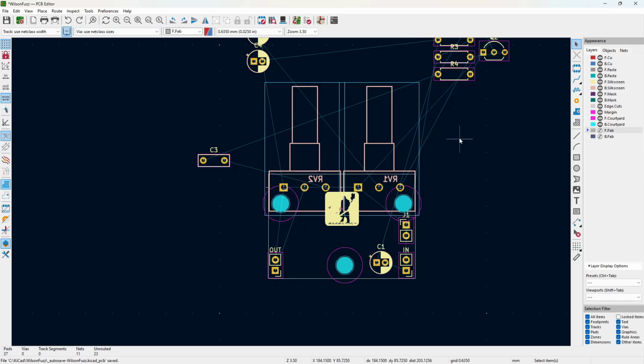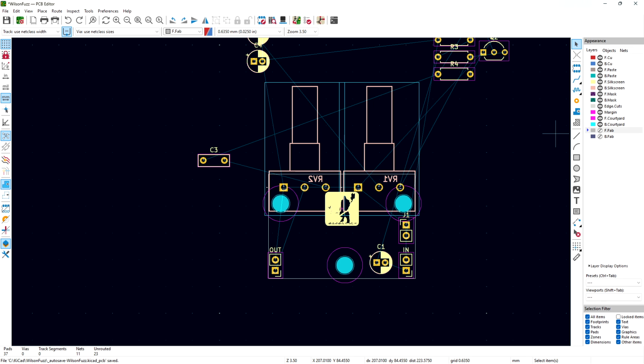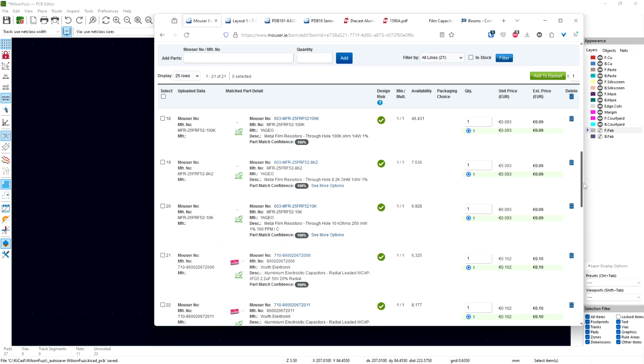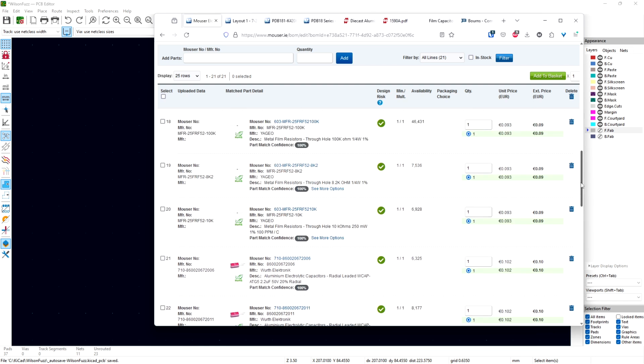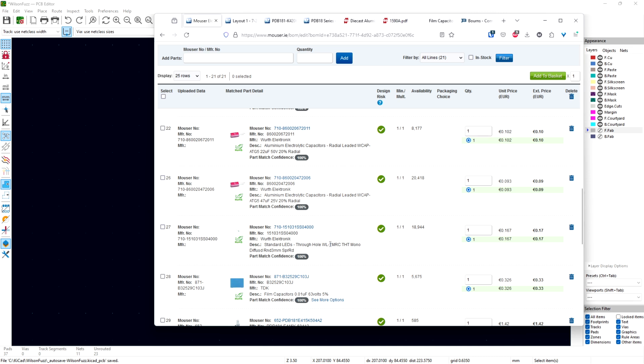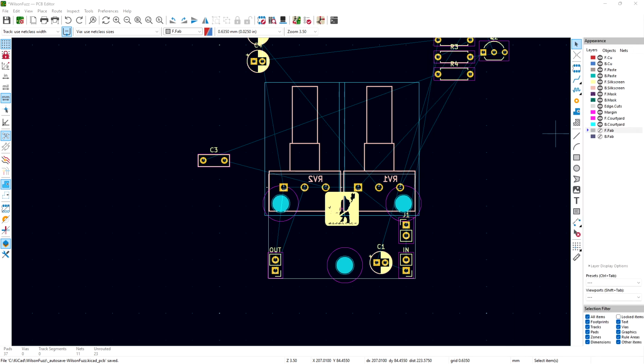Okay, but I only now realized that I forgot something. Remember I was talking about the LED, but I never added an LED. And did I add? Oh yeah, I added a 10K resistor here for the 3 mm LED. This is one of those low current ones, but I forgot to add the LED. So let me just go and rectify this.